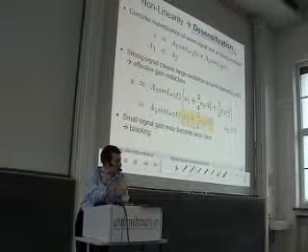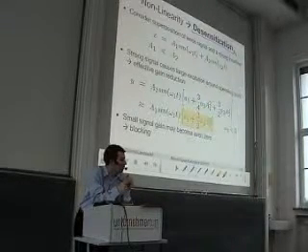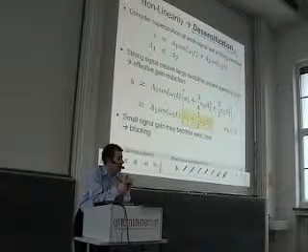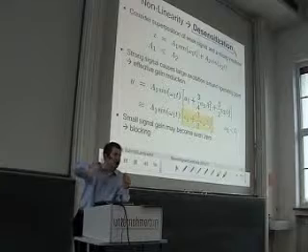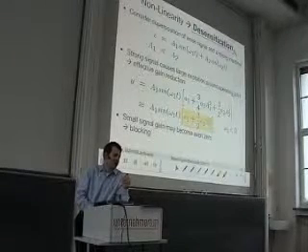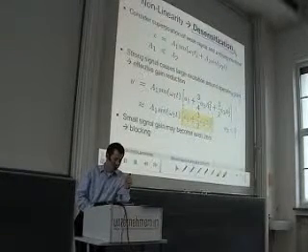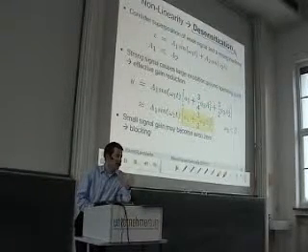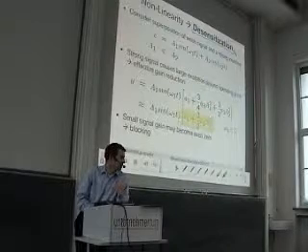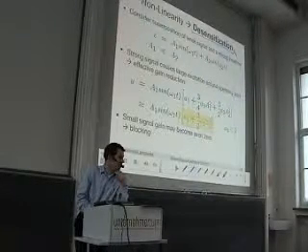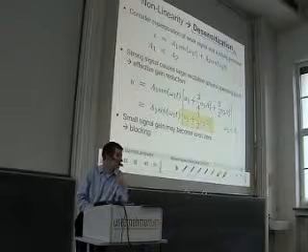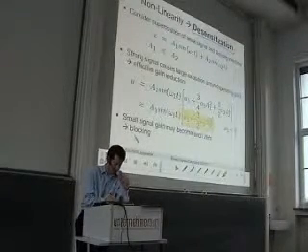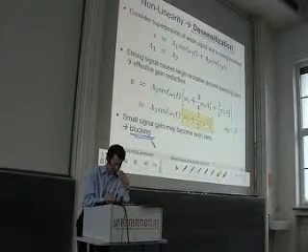And as the strong signal is disturbing the small one, we often call the strong one a blocker signal. Because due to the high amplitude, it disturbs the first one, due to the nonlinearity, so much that the gain seen by the first frequency is reduced to small values or even becomes zero. This is what people call a blocking of the first signal.